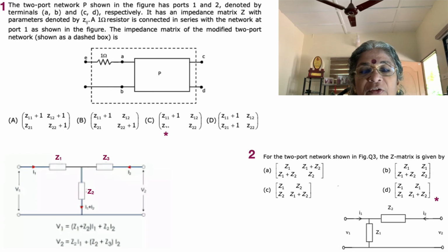What is it? For the two-port, of course, we are shown Z1 and Z2 only. So what we earlier called the impedance in port 1, exclusively in port 1, which is not shared by port 2, is absent, or the impedance is equal to 0. Obviously, if the impedance parameters are asked, as can be seen in the answers, Z11 is going to be 0 plus Z1. And Z22 will be, of course, Z2 plus Z1, and Z12 and Z21 are going to be the same and equal to Z1.